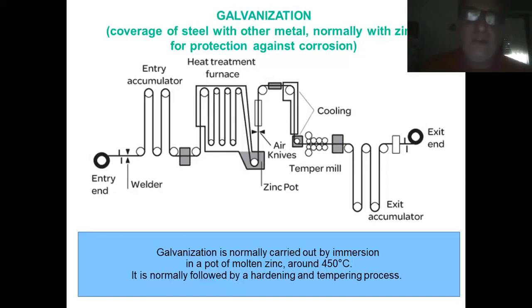Oxidation and corrosion are not synonyms because in the end you have an oxide, so it's oxidized, a passivated metal like titanium or aluminum, but there is no corrosion in the sense that there is no matter flying away, being brought away, and the material doesn't lose mechanical performance.